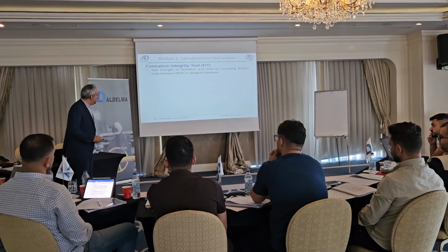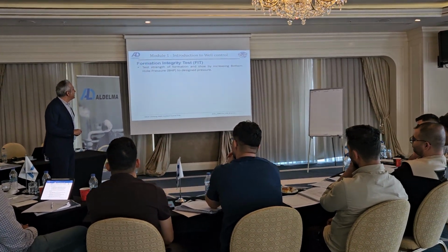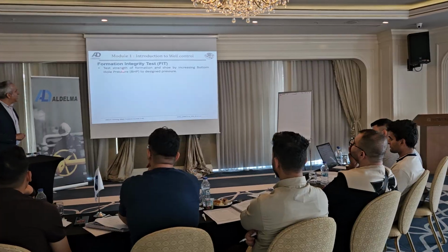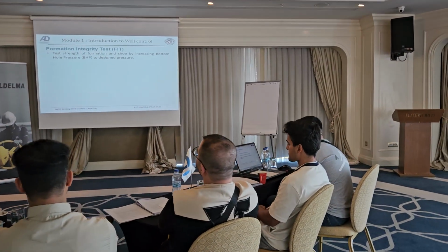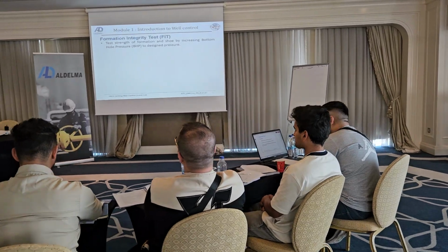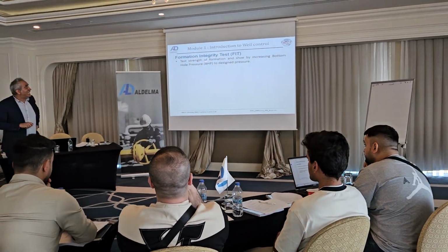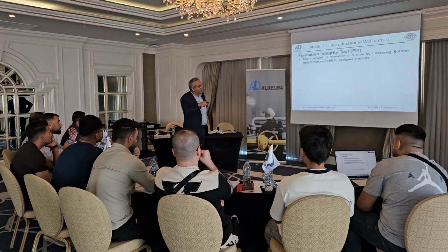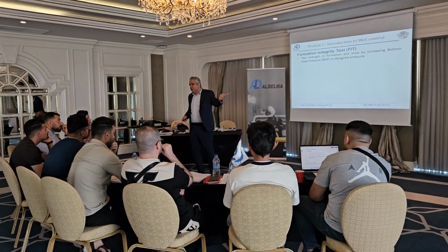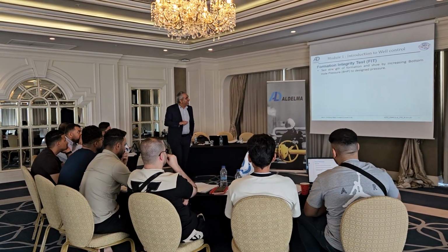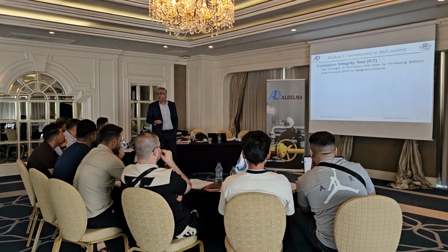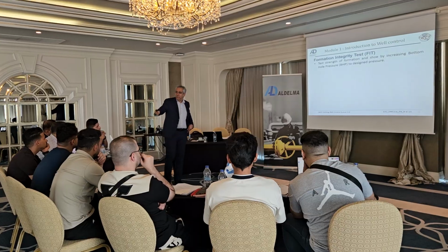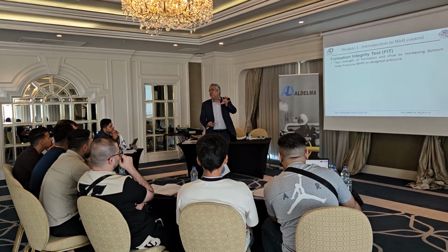I don't know. Okay, about this FIT, this is the test of the integrity of the formation at the shoe. We are not talking about the leak-off of this, yeah? That is the fracture gradient. Test the integrity of the formation. Maybe asking the question, yeah? If you look at all the sample examples, you will see: test the integrity of the formation at the shoe by increasing bottom pressure to the design pressure. You want to go to the next formation and say, okay, we can continue.